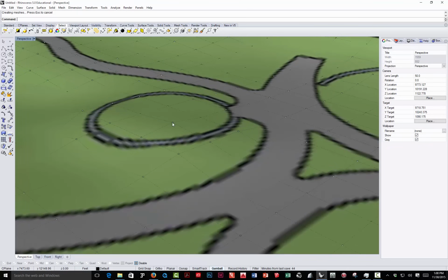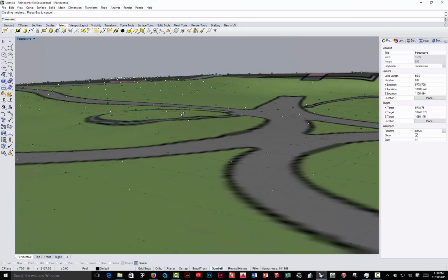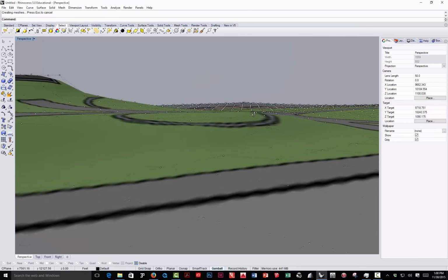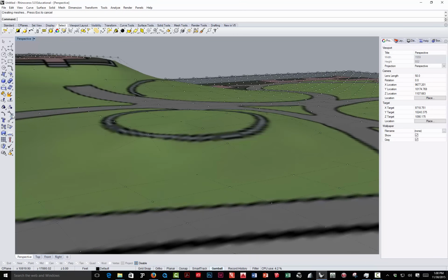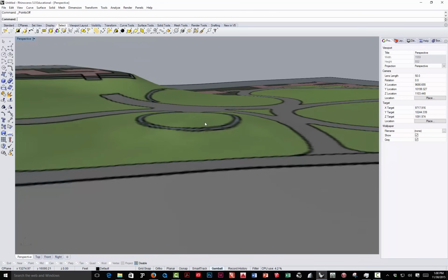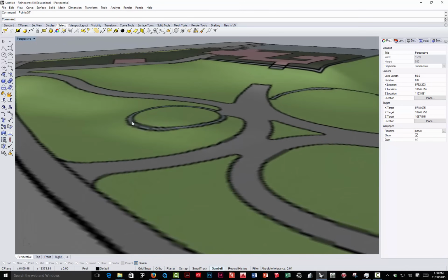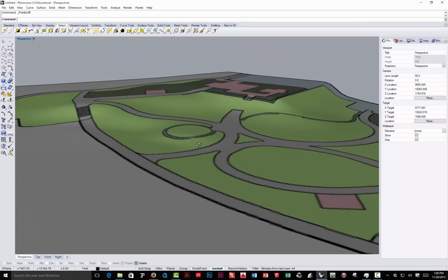And again, if you find one's a little too high in there, you have to look at the surface, because that control point is not on the surface in that case. So if you really want to look at it, I can right click, turn that off, and if it looks pretty level, again, the boulders are going to be in here, they can pick up some of that slope right there.